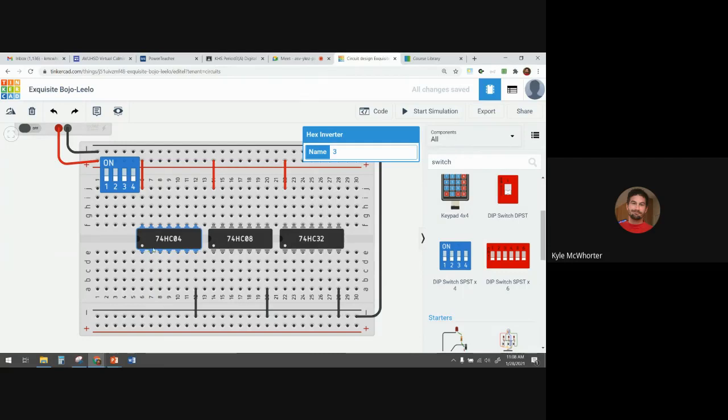So I will run a jumper across here for X. I'll make all my X stuff orange. So then I need to go from here over to input 1. I'm going to run a wire from the input 1 row over to the row that I had my X switch on. So whatever signal is coming down here, X will go in input 1 and come out here, not X.